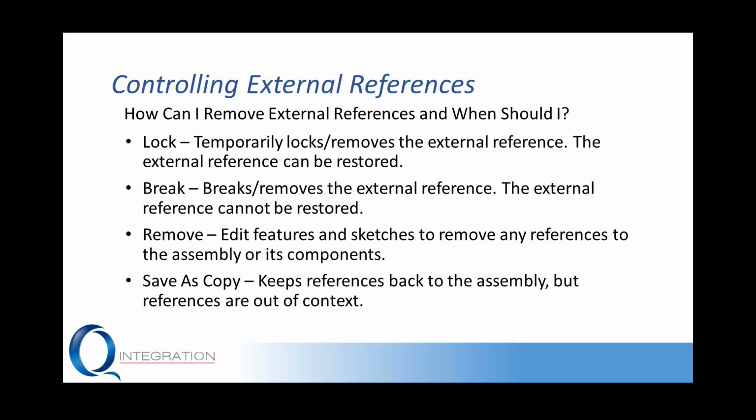The clean way to do this is to actually find where that external reference is, why we've created that external reference. Is it a feature? Is it inside of the sketch? Do we have relations relating to other components in the assembly? We want to find that and then utilize the tools in SolidWorks to remove those references. So whether it's deleting the relations and redefining the sketch using internal relations and dimensions, however we want to do that, we can go in there and remove those manually, and again, that is the cleanest method.